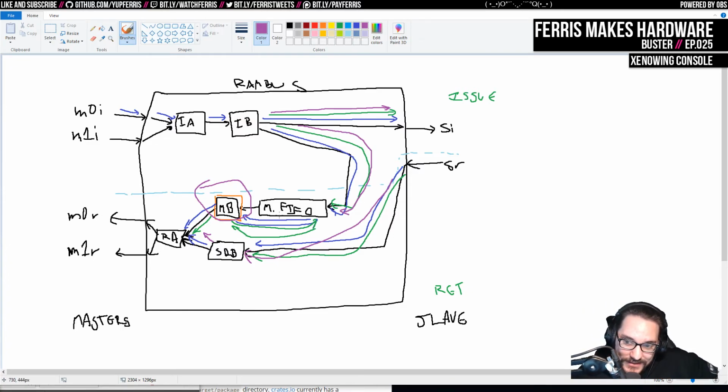And again, this has to do with this read latency coming out of this FIFO. It feels like we have this one cycle latency, where things bubble through this FIFO with a one cycle latency. And because this one doesn't have the same one cycle latency inducing FIFO, even though we added write through for this, that only really works for that first cycle. And then after that, we get that other cycle bubble while we have to read from this FIFO while data is coming out of this buffer.